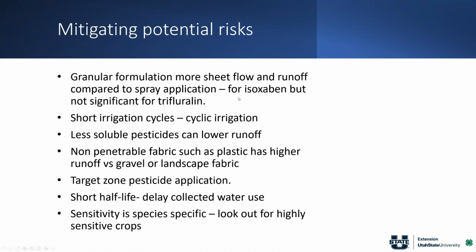But again, it depends on the pesticide. For isoxaben, there was high runoff with granular formulation, but for trifluralin, it was similar, either you apply granular or spray. But again, shorter irrigation cycle. So if you can go with cyclic irrigation, so going once and stopping and then making a second application, that way the pesticide can get adsorbed to more soil particles, and then it's less likely to run off. Less soluble pesticide can lower runoff concentration.